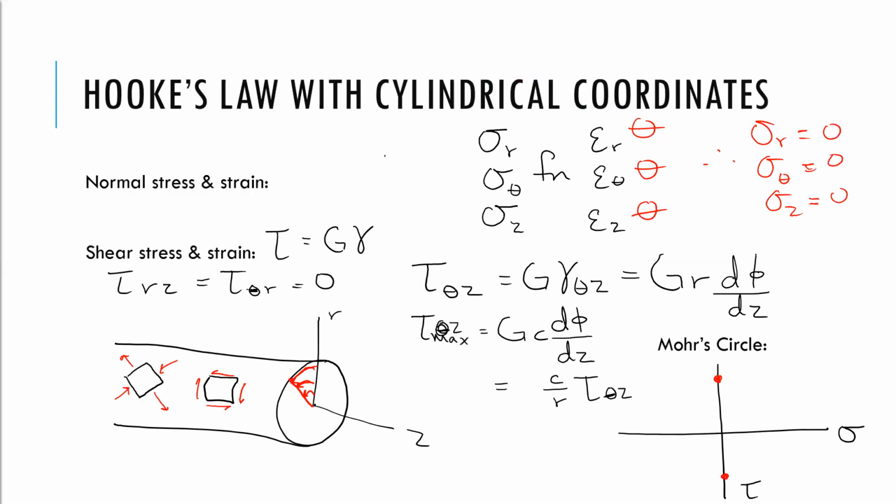But just remember, you always need to make it into a circle. Okay. You have your sigma x is 0. Plot that with tau xy, so you get that point below. Then, assuming that we have positive shear stress, and then your sigma y is 0, plotted with negative tau xy, so that gives us the point above, and then we make our circle.